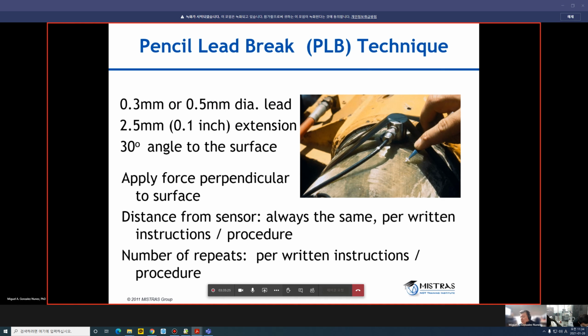Yes. At the beginning, before you start the acquisition, and at the end. At the end? Yeah, to compare the amplitudes of the sensors. That will tell you if the sensor moved or was affected by the acoustic emission test.